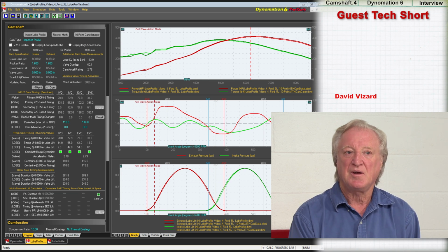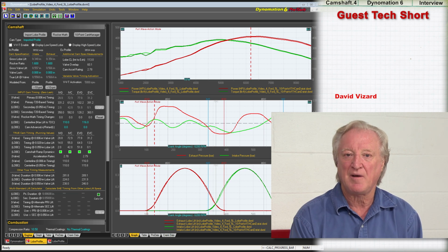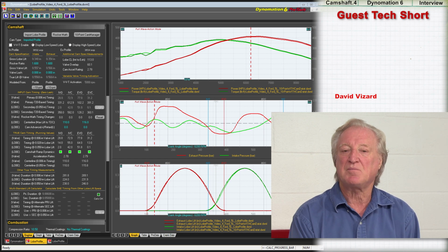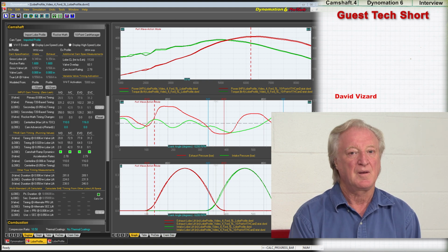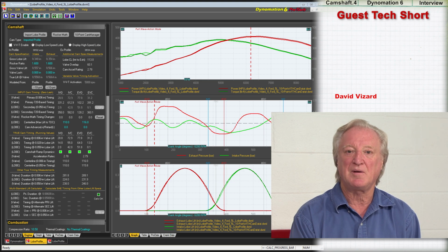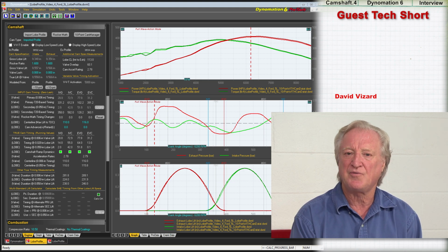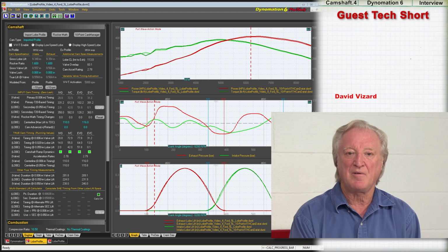That process has relegated the intake valve closure point to something like 3rd or 4th on the list of importance. It's still important. Every valve event is important. But if that overlap period is not utilized to its fullest extent, what can be given away amounts to a huge amount of power and torque.